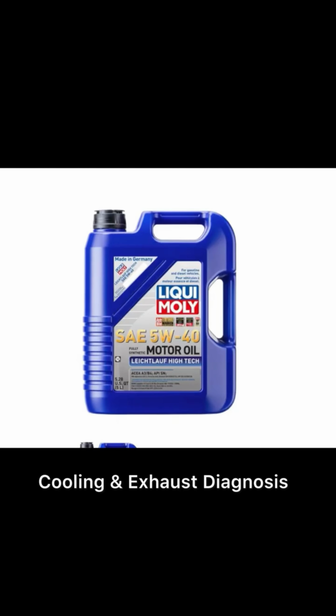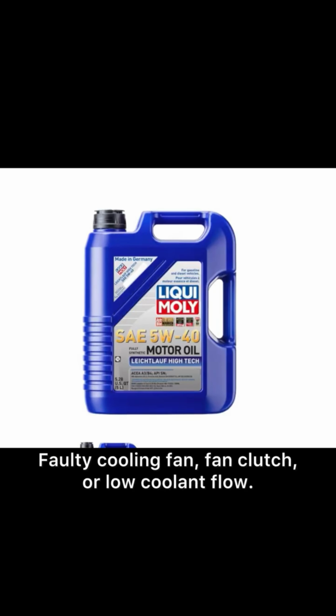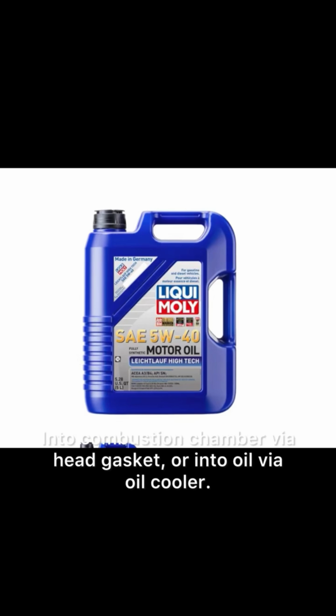Cooling and exhaust diagnosis. Engine overheats at idle but cools at highway speed. Cause: faulty cooling fan, fan clutch, or low coolant flow. Coolant loss but no visible leak. Where could it go? Into combustion chamber via head gasket, or into oil via oil cooler.